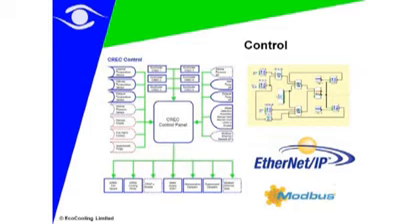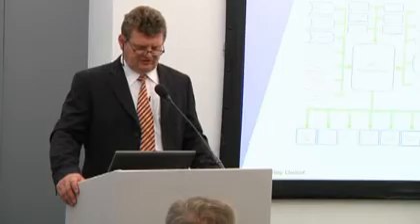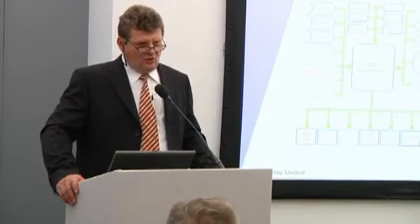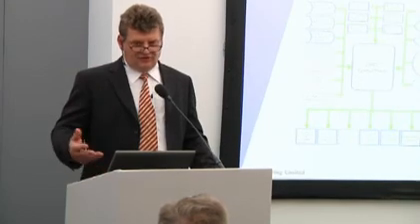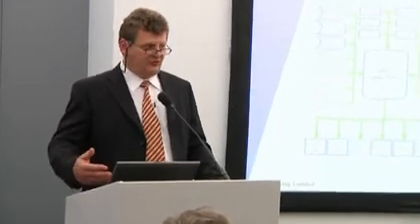We can measure true temperatures and true pressures and true conditions, and that's all linked together with also this facility for either Ethernet link into your existing network systems, or if you're using building management systems, Modbus to communicate in one direction all the operating parameters of temperature, pressures, fault conditions, etc. And as an input, temperature set points, alarm conditions, fire alarms, smoke alarms, fire suppression, purge requirements, etc. All linked together on one common control system.